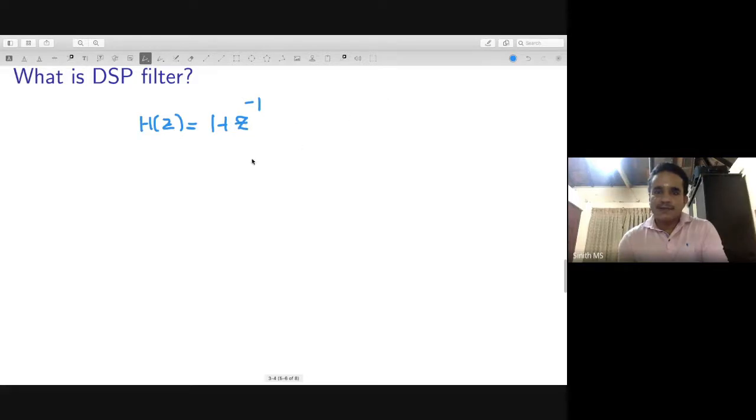If you write H(z) as Y(z) by X(z), which is 1 plus z inverse, then Y(z) can be written as X(z) plus X(z) into z inverse.